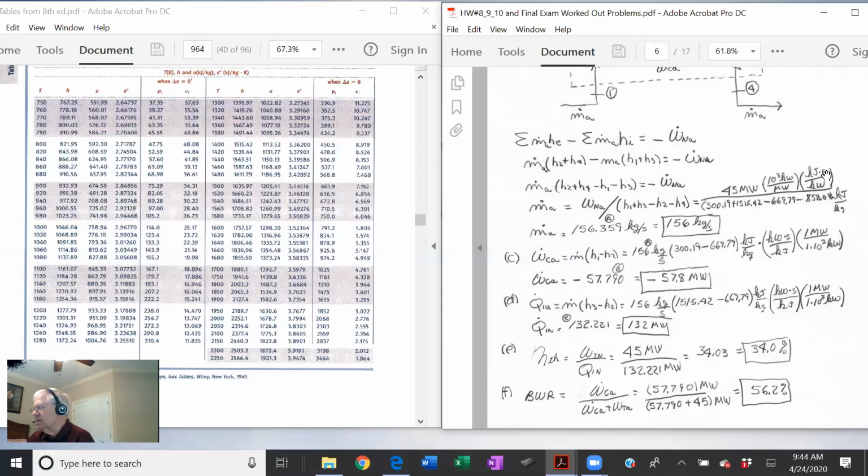That second should be right here by the kilowatt, because a kilojoule per second is a kilowatt, and it would come out just right here. So I got the mass airflow is 156.359 kilograms per second, rounded off to 3 significant digits for the final answer to present.